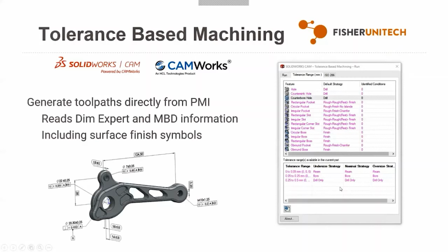If you've worked enough in production, you know to account for things like tool wear, especially on a tolerance like that. If I'm making 30 parts and I've got that one reamer that it wants to suggest, how much tool wear am I going to have on that reamer, and how much can I expect over my 30 parts? So this allows you to either undersize or oversize and move towards the mean as you continue with your production run.